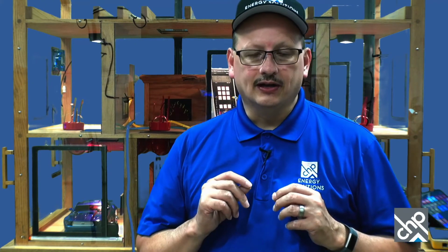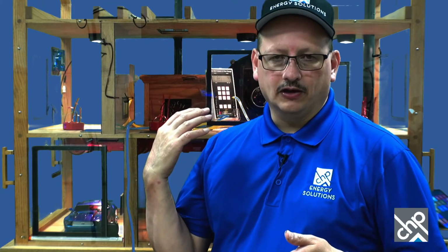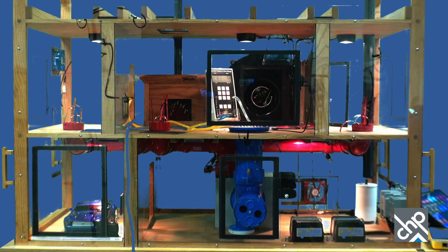And so what we're going to move to next is combining all these things together and doing a little CAZ pressure test. Of course, the CAZ, I call it the combustion safety test. You're looking at the chimneys, doing gas leaks, carbon monoxide, efficiency, temperature rise, ideally even static pressure and things like that. But what I want to focus on is just doing the CAZ piece. I'm just going to say that we have a CAZ upstairs, and then we're going to go through the steps to make a worst case scenario. Okay, that's what we're going to do next. I'm going to turn everything off and wipe the house down here a little bit.